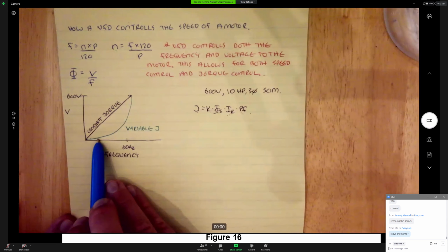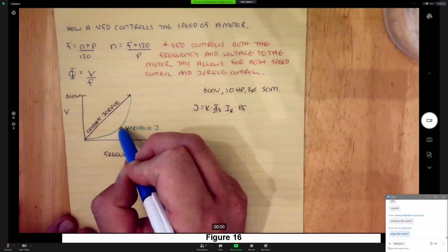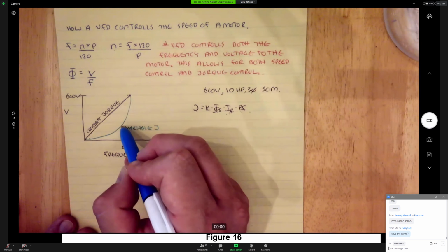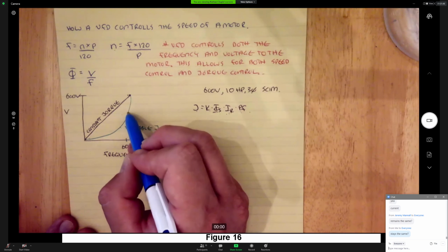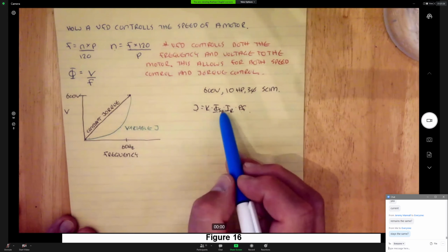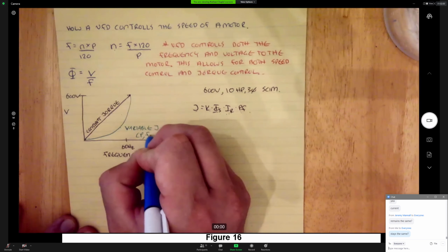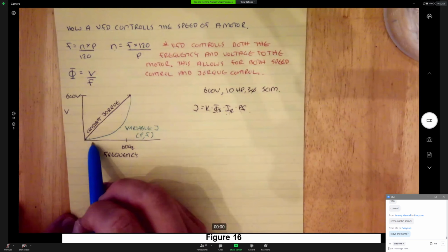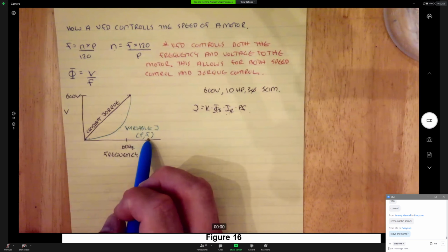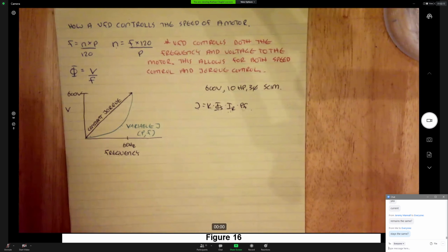So we don't start with a whole lot of torque, but right about this point, now it starts to increase the other way. Now frequency is not increasing as quickly, but the applied voltage is increasing more quickly, which causes an increase in flux, which causes an increase in torque. So the reason why this has its application mainly in pumps and fans is the reason I identified before. When you first turn a fan on in a building, there is no load, there is no resistance, because there is no static pressure in the ducts inside that building being fed from that rooftop unit.